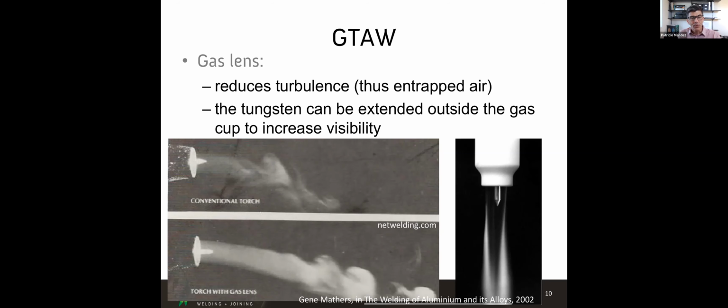So an important lesson from this course you're taking is if you want really good shielding, you don't necessarily need to put more gas. If you have too little gas, you need a little bit more gas. But once the gas is right, if you have problems of shielding, you do not solve them by increasing the amount of gas.